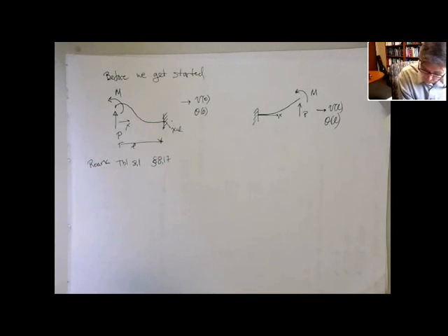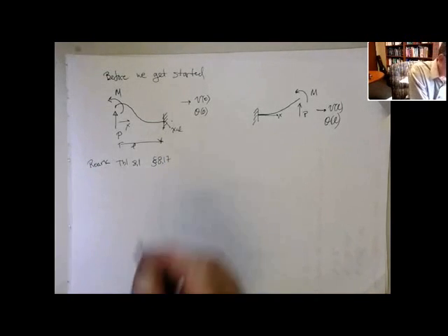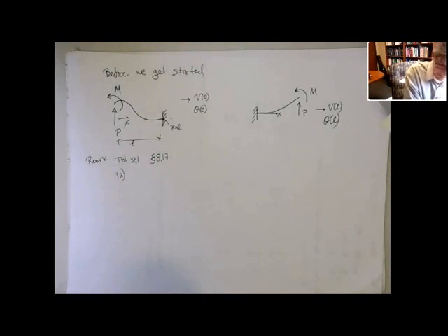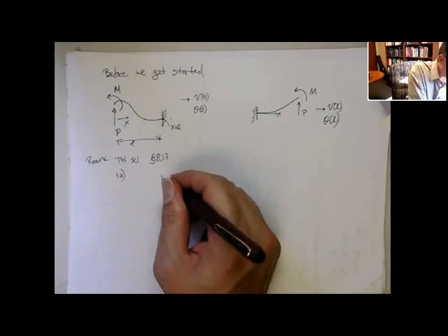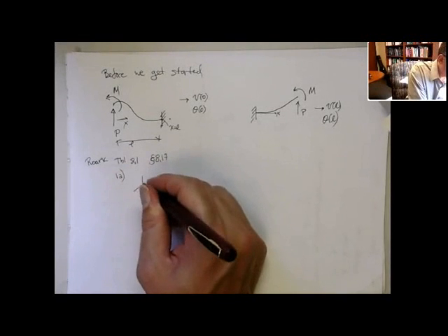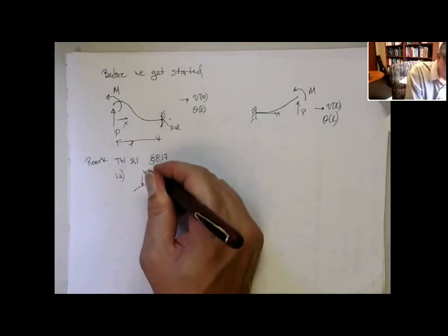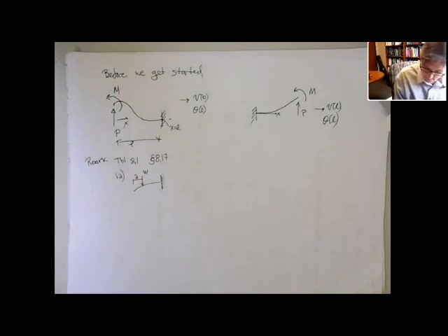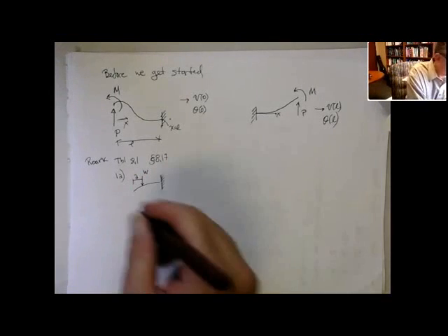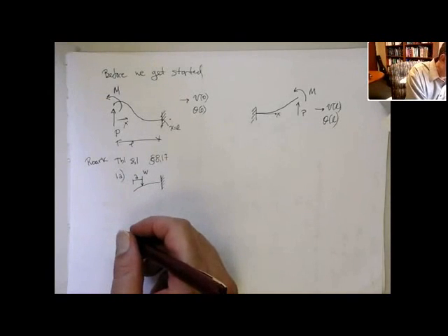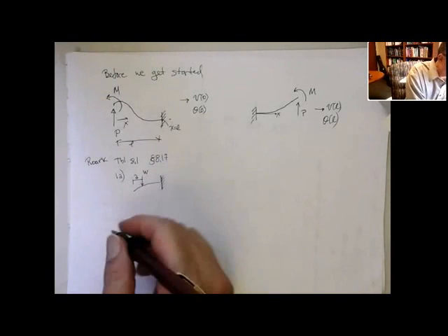And we look at case 1A. It looks like this: a beam bending down, with a point load W at some distance A, and a length L, and all that sort of stuff. So it's cantilevered, close to this, but it doesn't have the moment. In our situation, we're going to let A equal 0.